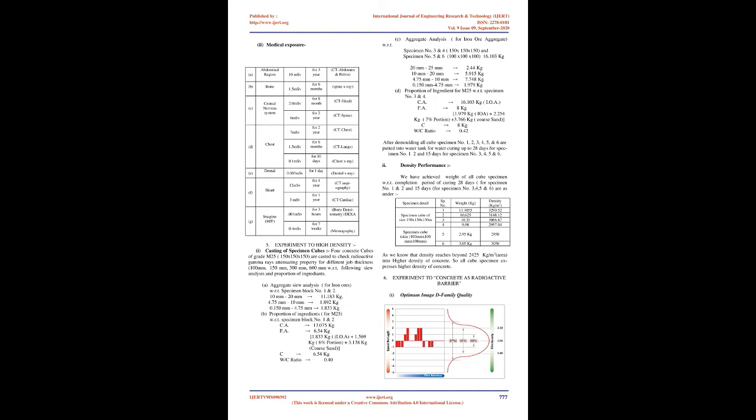Properties of high-density aggregates and concrete. Ferrophosphorus density, kg/m3, 4080-5290. Steel punchings or shot density, kg/m3, 4650-6090. 2. Sample casting. Mixing, curing, testing of specimen.